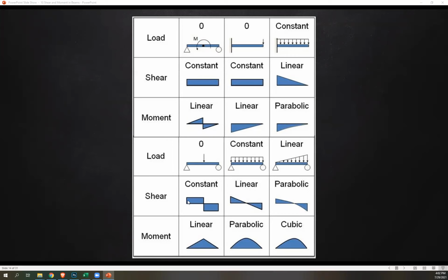Okay, a good example is this. This is up. This is your 0 mark. So positive, so this is upward. Then here negative, so this goes downward. And another thing, to know if you got a correct moment diagram, usually you're going to start at 0 and end at 0.